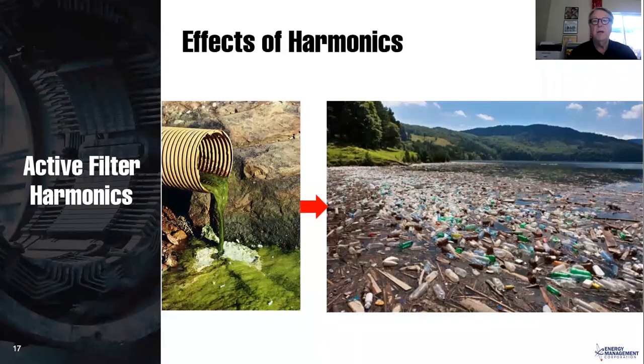Harmonics are pollution. They're like any other sort of pollution. You put a little bit of harmonics in, you get a little pollution. You put a lot of harmonics, you put a lot of pollution. So it's very common, and somebody may come out, want to sell you a variable frequency drive, and they'll say, look, you don't need to worry about harmonics because look how small this drive is in comparison to your system. And they're right. But what about the next drive and the next drive and the next drive after that? Eventually, you end up with a polluted system. In general, 100 1 horsepower drives is going to pollute about the same as one 100 horsepower drive. So generally, we're less concerned about the smaller loads and more concerned about the larger loads.